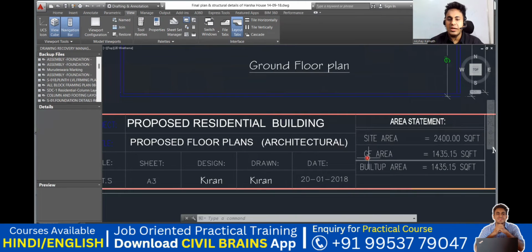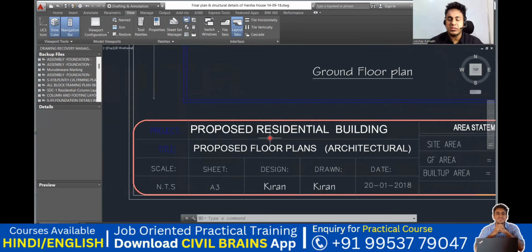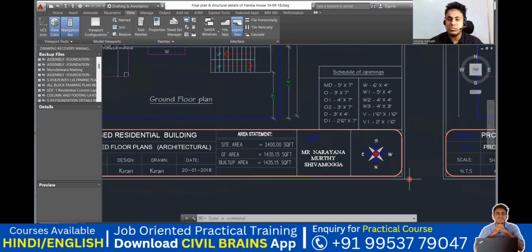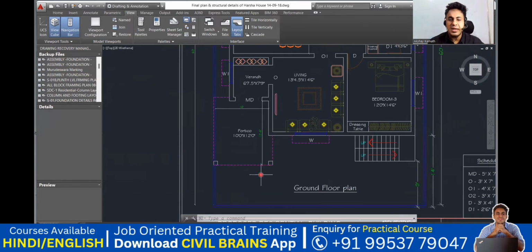Okay, and only a ground floor they have put up here. It's a proposed residential building, and who has designed it, who has drawn it, and the date on which this particular drawing has been done, each and everything will be mentioned. Of course the direction has to be mentioned, like this is north, south, east and west. And then the schedule of openings, like main door, the doors, the ventilators and the windows. So we'll start with this again.